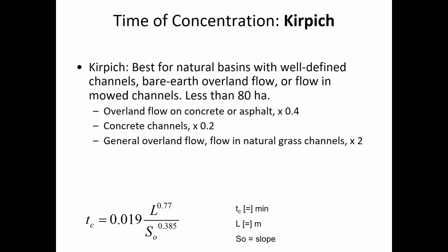In the parking lot, there will be some places where more of the water has come together in a single spot, and it's not a channel or anything, but it's just what the name describes. It's shallow, but it's concentrated flow, where several of these streamlines have come together. And then the last among them, channelized flow, would be like a stream, a creek, or a gutter, where it's clearly intended to move the water from one place to another. And it's going to be deeper than maybe 1 centimeter.